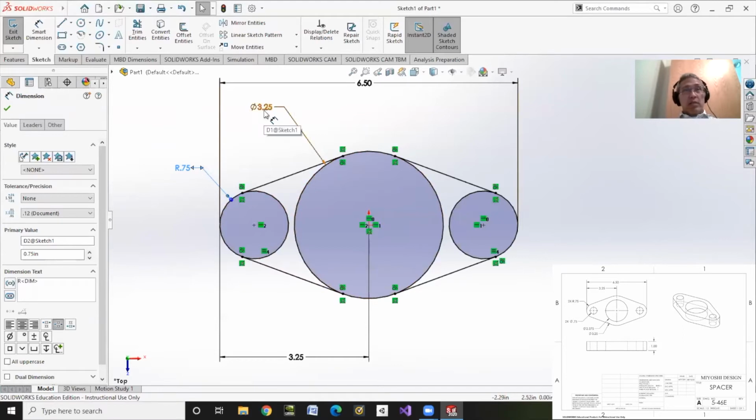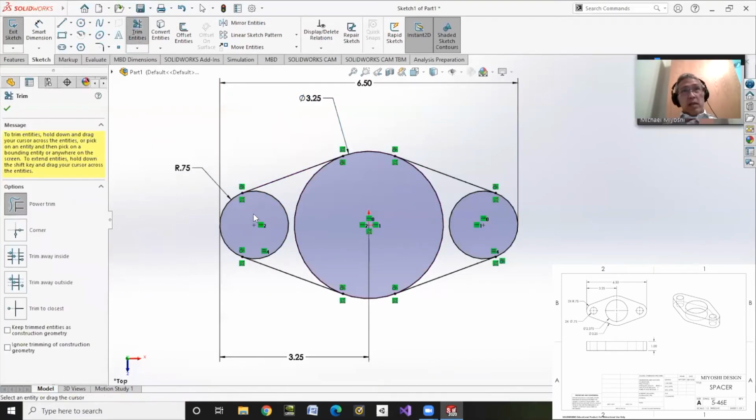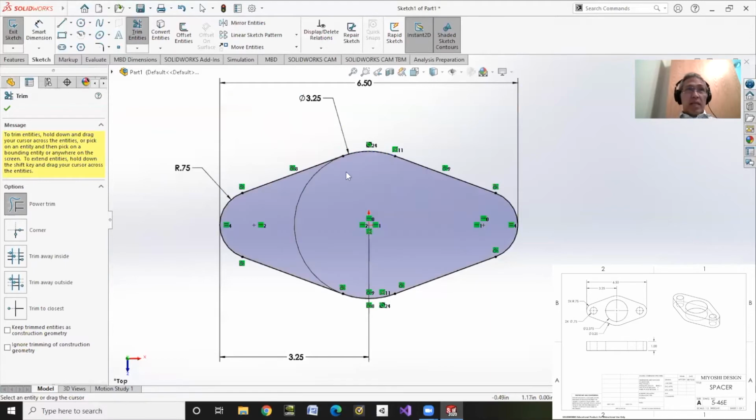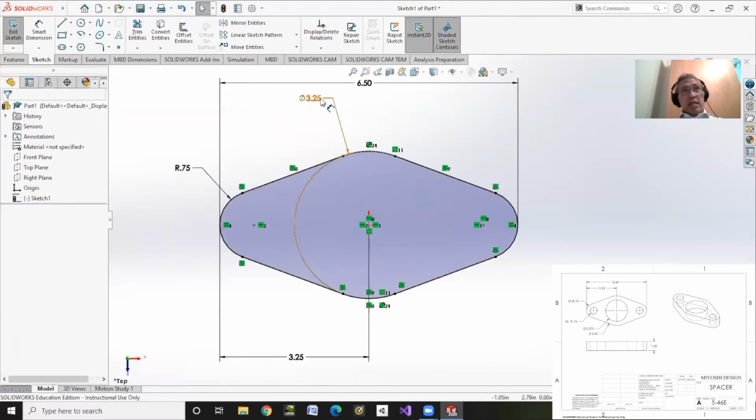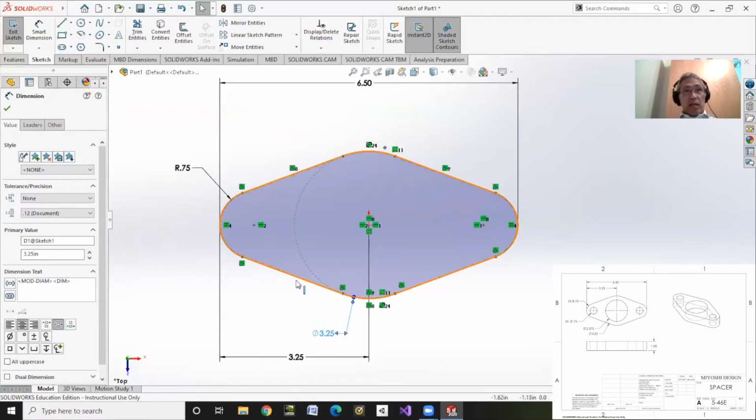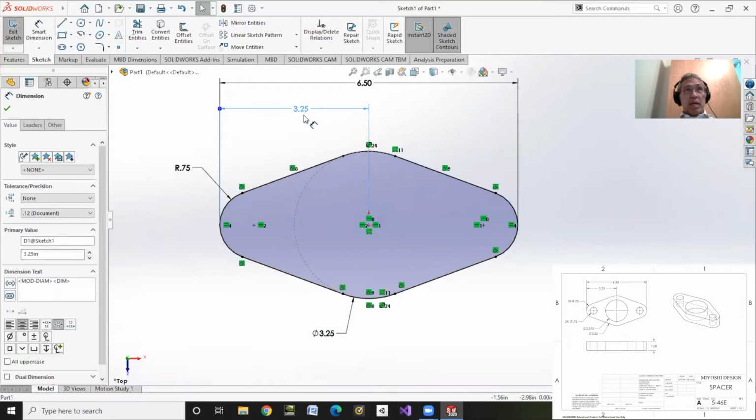Now, I said before that you don't want this to be too close to vertical, but I don't want the big, huge line here, so I'm going to change this a slight bit and make that there inside the coincident point. Then I'm going to go ahead and trim edges, and I'll click and drag all the way across to this side. Now, notice it looks like there's another line still there. Well, it's not really there. What it is, if I click on the check, it's actually this dimension line. So if I move this down to the bottom instead, it'll actually look better. Now it shows as a hidden line. And if I really wanted to, I could pull this guy up to the top, and that's probably a little bit better. Okay, so that's the outside of the figure.